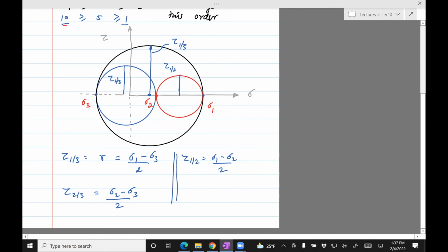So a typical procedure would be, if you have a general 3D stress element, you first draw the 3 Mohr's circles. You first either draw the 3 Mohr's circles or find the 3 principal stresses and use the extremes, sigma 1 and sigma 3, to find the stress which is most important. And then you proceed with design using the maximum stress. And this is something which will come up again when we talk about designing shafts for different loads. Okay. So we'll